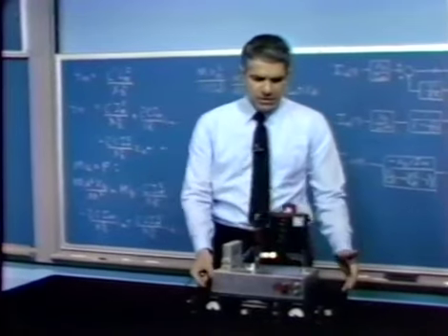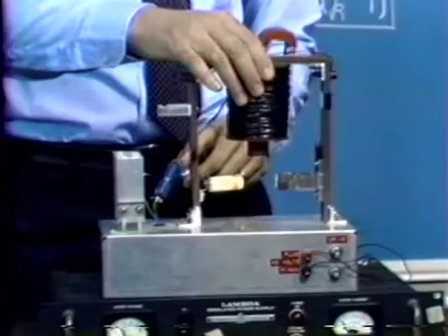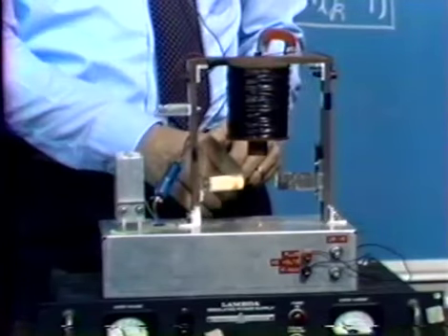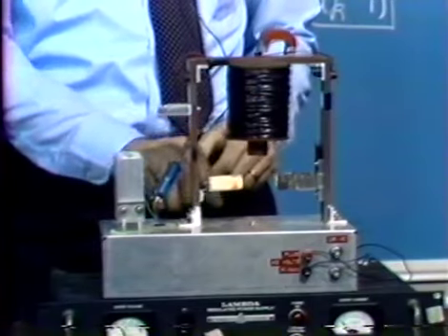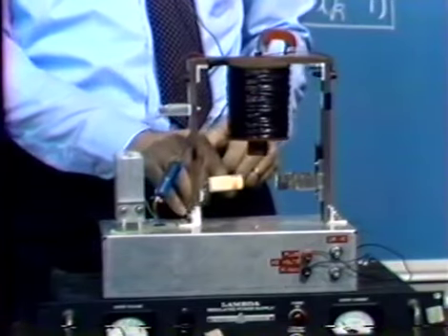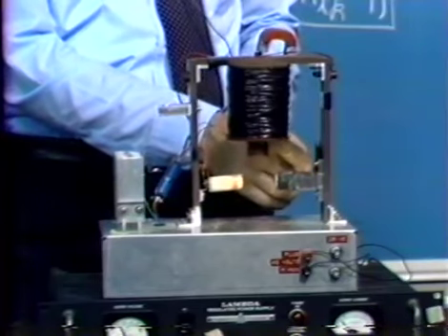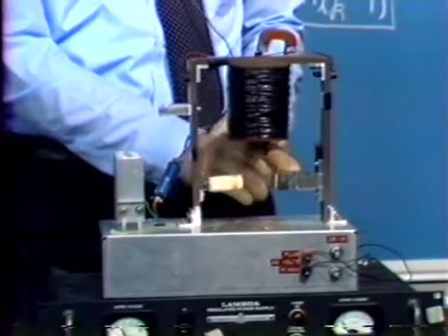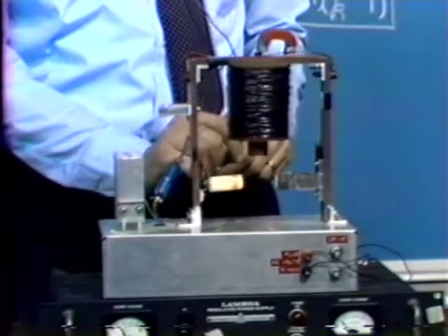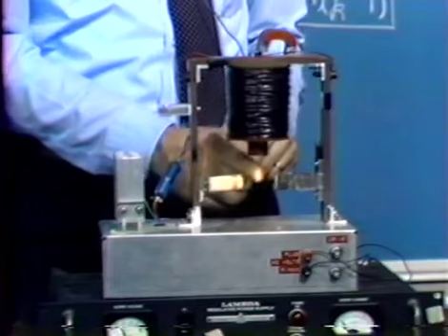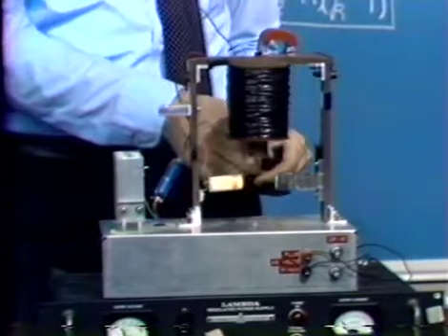Here we have, as the base, simply a power supply. There's a large electromagnet that you can see. There's a sensor which is optical, and it consists of a lamp here with a little bit of a shield, very primitive optics, just a piece of cardboard wrapped around the lamp. Over in here there's a photocell, actually a photoresistor, that has a linear sensitive area possibly 1/4 or 3/8 of an inch long, and again extremely primitive optics, simply a washer in front of the thing.